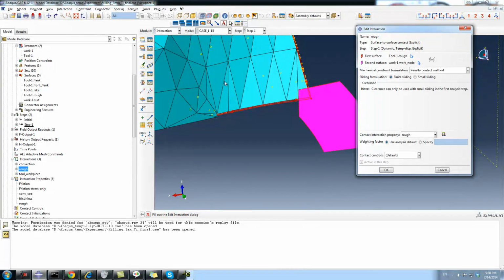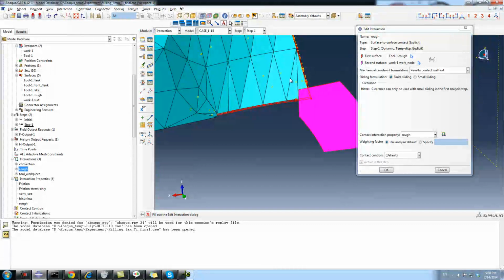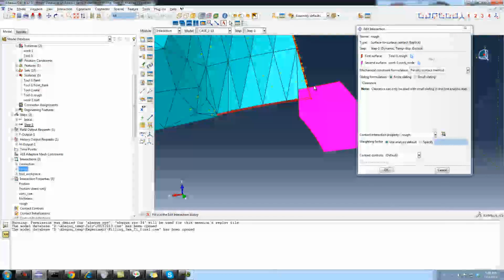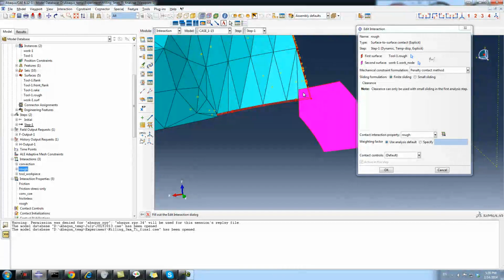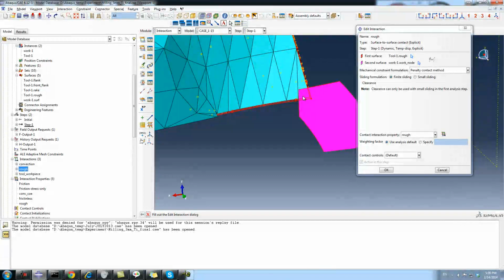Why do you give rough friction only to this one edge? Rough on the edge, and this has some friction coefficient. The workpiece can flow on this rake face, but it will stick at the edges. Actually, the stick length should be 1/3 of the depth of cut, but that was creating problems. So I reduced the stick length. You only use that rough friction for a small portion.